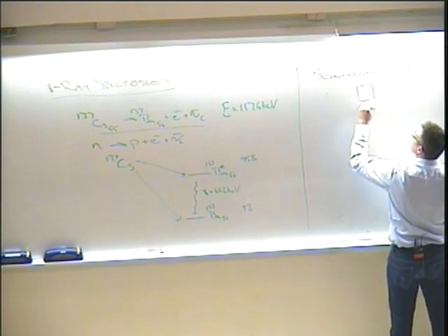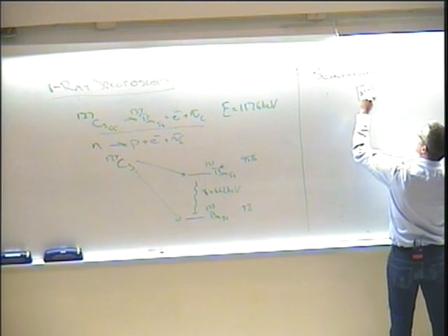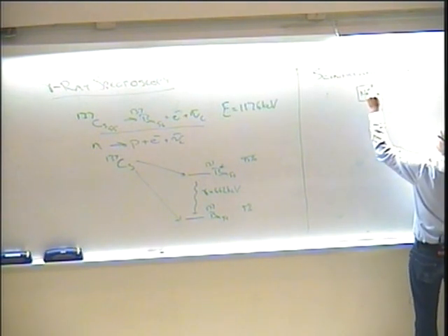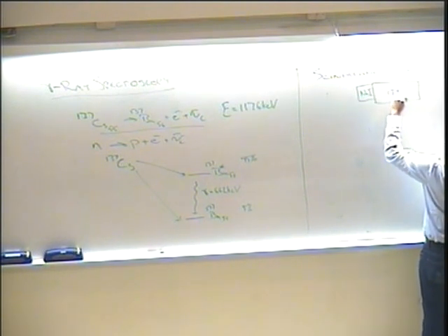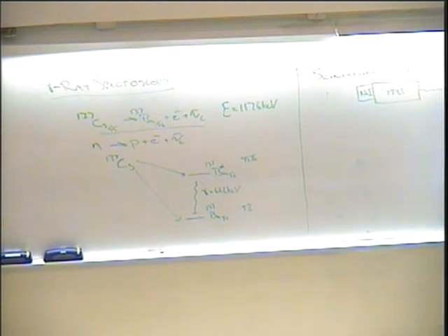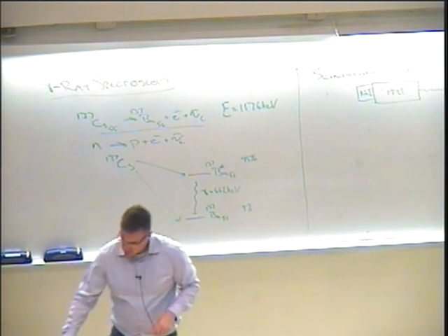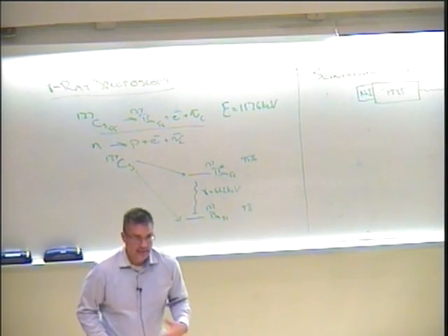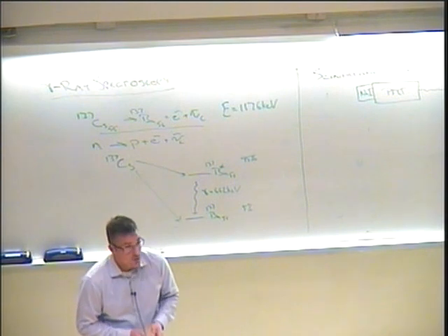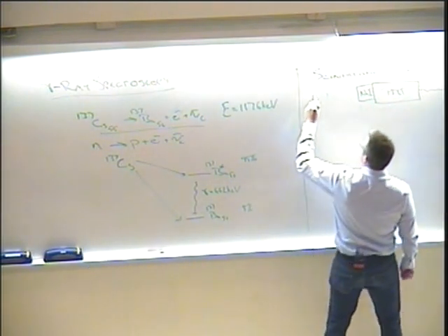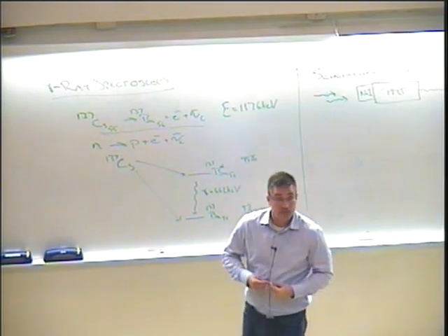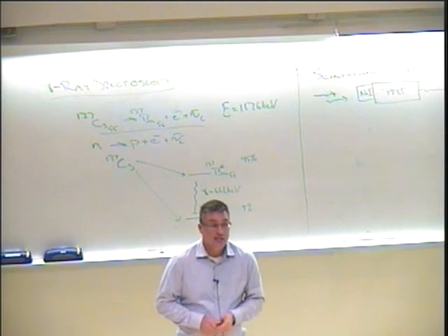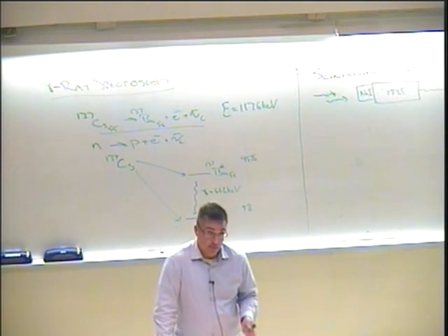So we have our crystal, and on the back of this is a photomultiplier tube. And that goes out to your detection electronics. Okay? So the idea with this detector is that we're going to take a bunch of incoming gamma rays and we're going to convert them to something usable, something that we can say is proportional to the energy of the gamma rays.